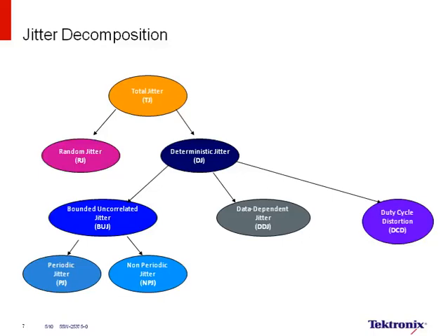The key thing to understand is the reason for the jitter decomposition. There are two main reasons. The first is a language of communication. In general, correlated jitter can be corrected through techniques like equalization. In general, uncorrelated jitter cannot be directly compensated in an equalization system.